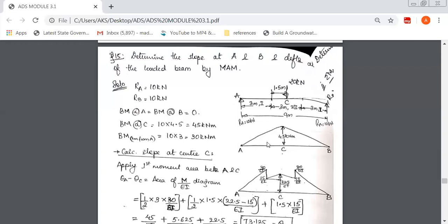So accordingly, the bending moment diagram is 30 over EI at this portion, 3 meter. On the left side, I divide by EI to get 30 over EI. Similarly, on the right side, the same 30, I divide by 2EI. So 30 divided by 2 is 15 over EI.